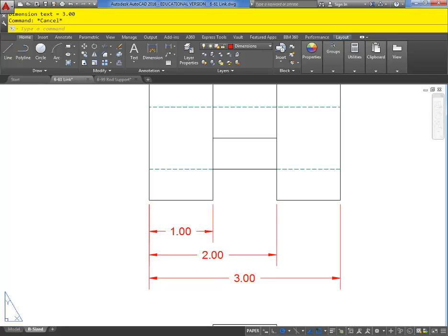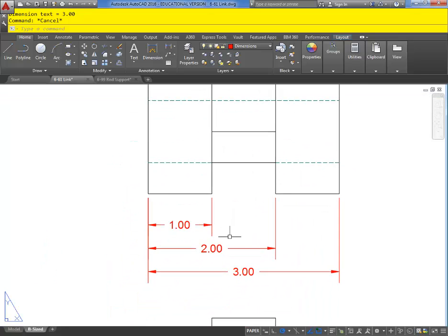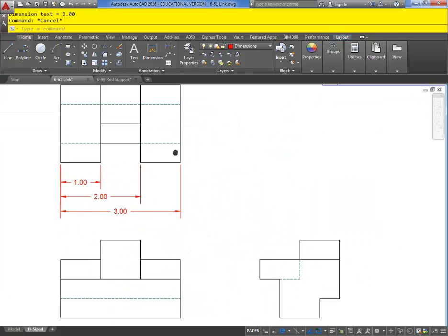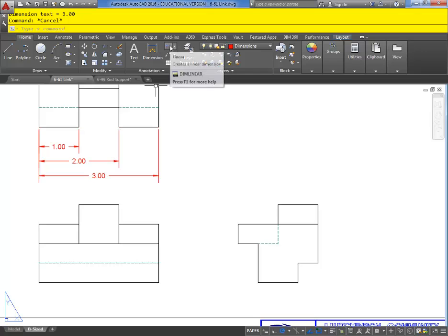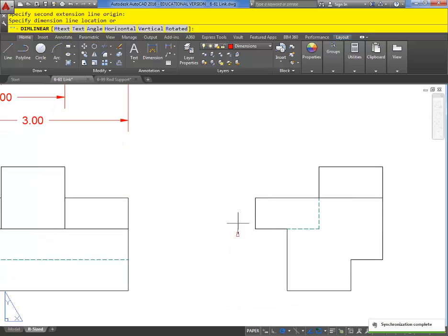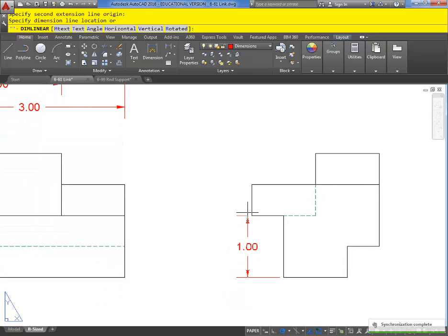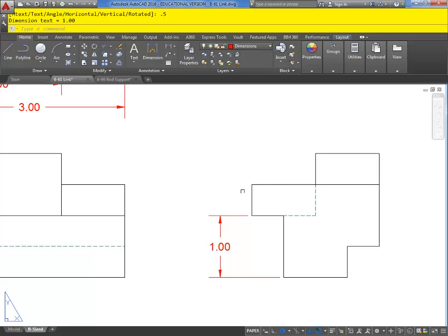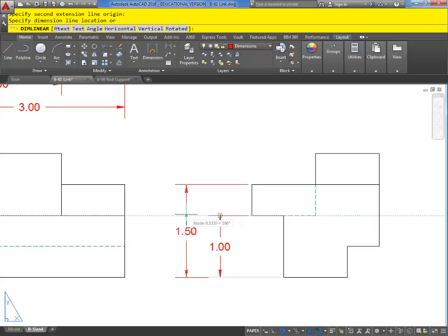Now sometimes, especially if we're going out to the side, you might end up with some values that are close to the lines. Let me see if I can give you an example over here. Let's just say from here to here, and then I'm going to track off of that. And by the way, it needs to be a 1/2 inch away from the outermost point. So 1/2 inch from this one, not that surface. So I'm going to see if I can track off of it. 0.5, good. And then I'll do another one. Again, I'll track off and go 0.37.